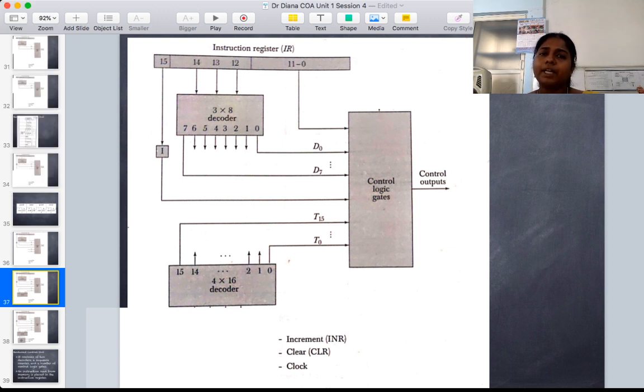So I have completed my instruction execution within 3 clock cycles, and at T2 the execution is complete. In the next time cycle, I have to start afresh and execute my next instruction. For that, I am going to use the clear input to state that the instruction is complete and I have to start generating from cycle T0.